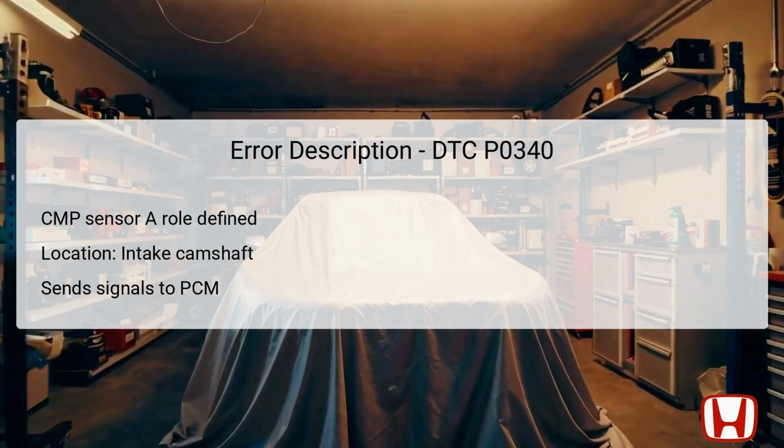The CMP sensor A is essential for managing engine timing. Located at the intake camshaft, it monitors the camshaft's position and sends this information in the form of pulsing signals to the PCM. This allows the PCM to adjust timing based on real-time conditions, ensuring efficient engine operation. If the CMP sensor A stops functioning correctly, it can't send these signals, leading to a condition where the PCM is unable to accurately calculate camshaft timing.